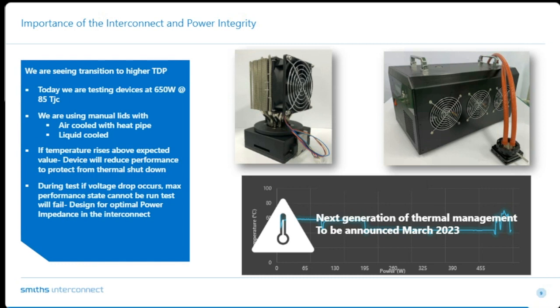These have fallen from 92C to 80C just a few years ago, and as low as 55C for a growing number of applications today. And this is a key problem in that removing greater volumes of lower temperature heat is super thermodynamically challenging.